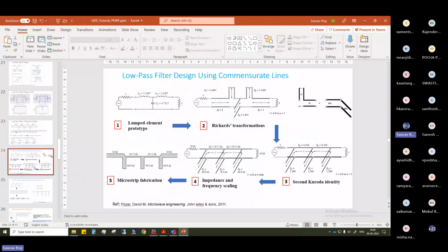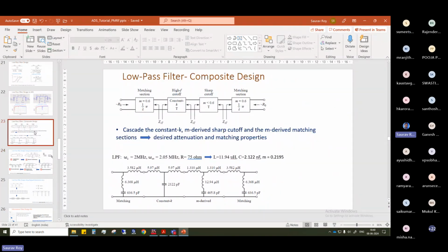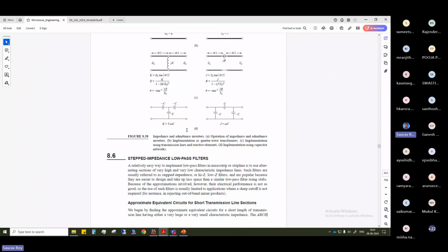Okay, if there is no question, now we'll move on to the next question. This is a first order low pass filter, right? Now let's say we have to design a third order Butterworth filter or a third order Chebyshev filter. How do we do it? If you remember the theory, the table already gives you the values, as I told you, G1, G2, G4, all these component values. From that, you just have to calculate your capacitor and inductor values, and then just do the simulation.